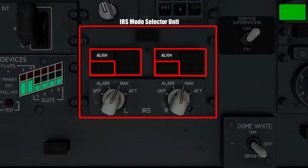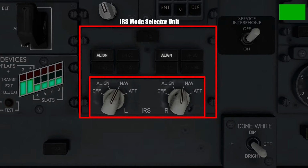Coming underneath, this fault light simply signifies a fault with that specific IRS system. On the right, this DC fail light comes on if the IRS systems are unable to draw direct current to be operational. As for this knob below, we'll talk about this in the electrical power up procedure video, where we will start these aircraft from a cold and dark state and do a full flight with it.